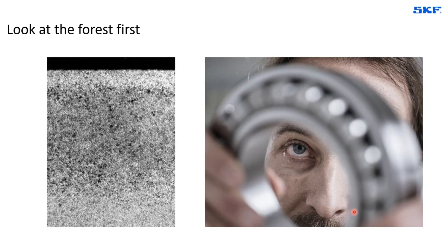For example, we need to look at the shaft, at the housing, at the covers of the housing, the seals, the seal surfaces, the lubricant, the foundation, and any other element, and even the bearing that was mounted at the other end of the same shaft. So we should never look at the details of the bearing in isolation. The bearing is part of a system, and it has to be looked at in that context.